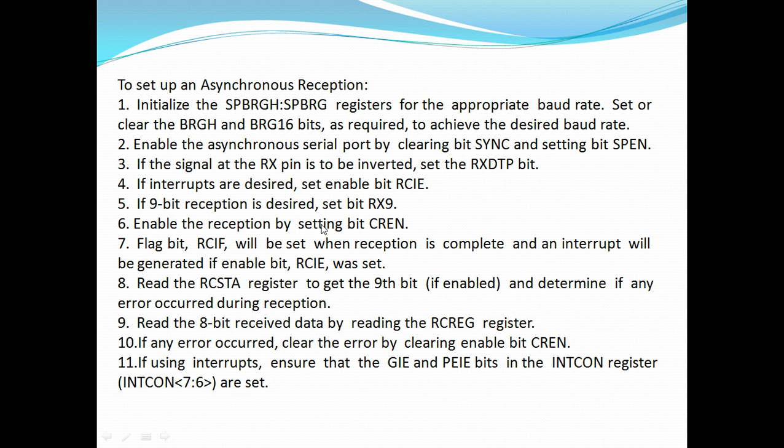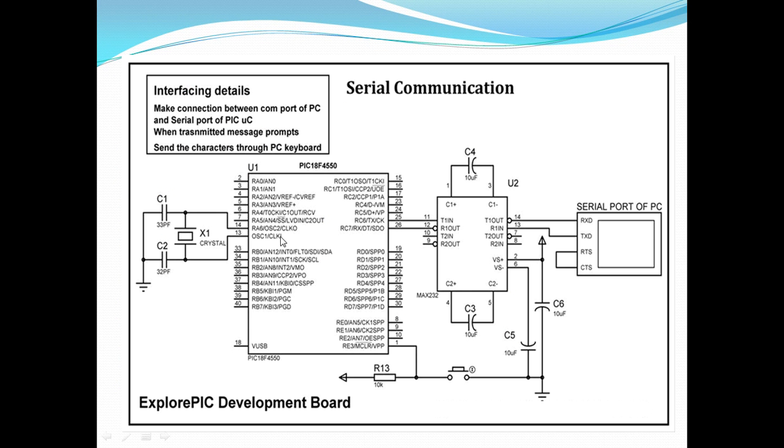For continuous reception we need to enable the CREN bit, the continuous receive enable bit. So with all these steps, like the transmission mode, we can set asynchronous communication.